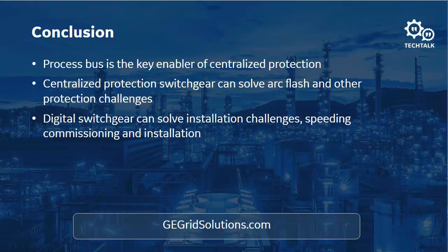How is an individual feeder's protection outage managed when using a single relay to protect multiple pieces of equipment in the substation? So I think that really comes down to the point of you probably will want some redundancy in your centralized scheme. Again, that's fairly easy to implement in either a point-to-point switched Ethernet process bus or even an HSR ring, because you've got one relay there that you need to have redundancy for.